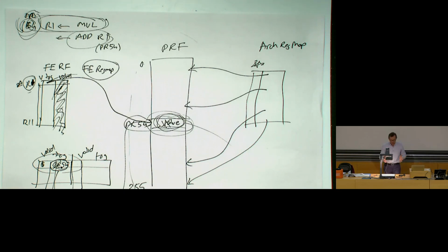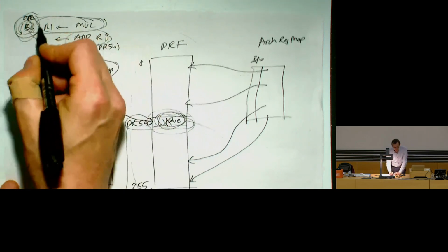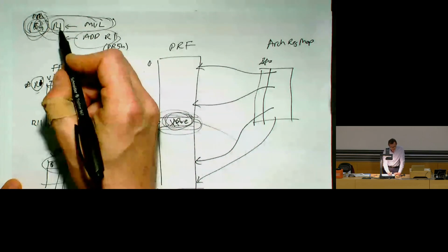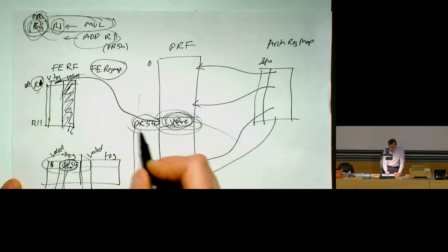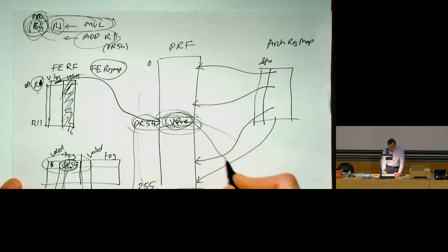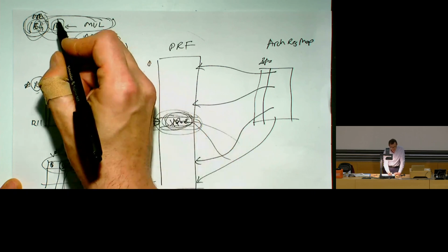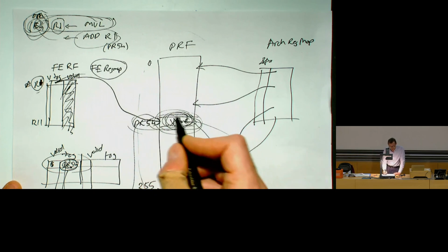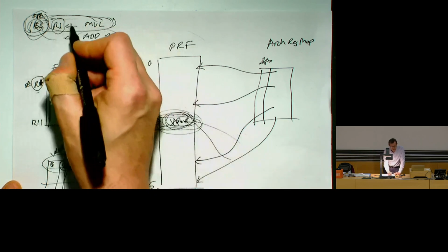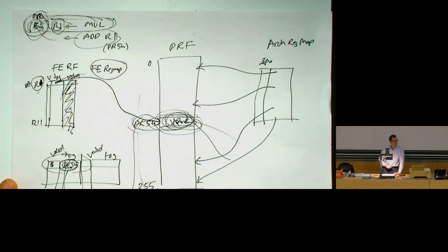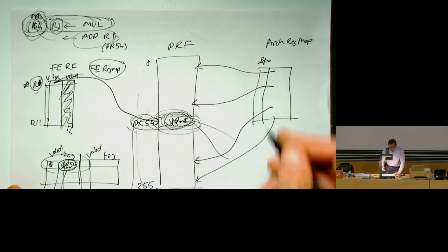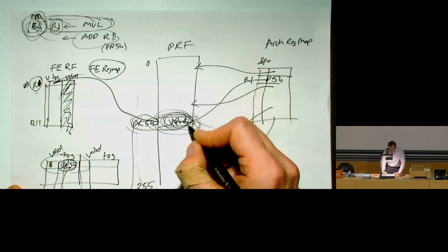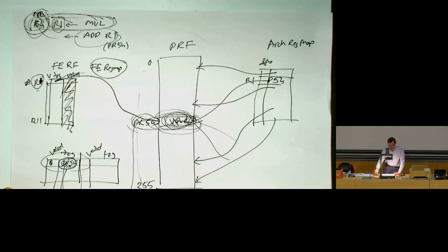And this makes sense, right? Whenever this instruction produced physical register 54, it wrote into R1. This instruction finishes execution. It writes into physical register 54. That version of R1 is actually here now. Now, when this instruction becomes the oldest in the machine, this physical register 54 actually houses the correct architectural value of R1, because this instruction finished, it's the oldest in the machine, which means that R1 should point to physical 54 over here in the architectural register file.